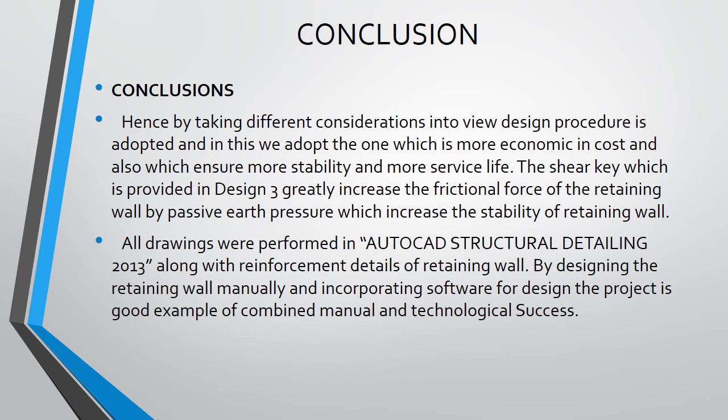Conclusion. Hence, by taking different considerations into view, a design procedure is adopted, and in this we adopt the one which is more economical in cost and also ensures more stability and more service life. The shear key which is provided in design 3 greatly increases the frictional force of the retaining wall by passive earth pressure, which increases the stability of the retaining wall.